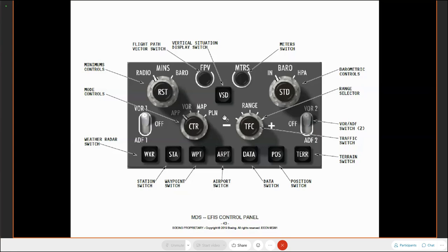Okay. We also have the center switch. There are many formats on these displays that allow me to change how we see that information, whether it's what we call an expanded view, where it's like a zoomed in view, about 120 degrees of a compass rose, or what we call a centered view, where it shows a complete 360 degree compass rose. Okay, information's the same, it's just shown in a slightly different way, possibly. Okay, so we can alternate between centered and expanded just by cycling that switch.